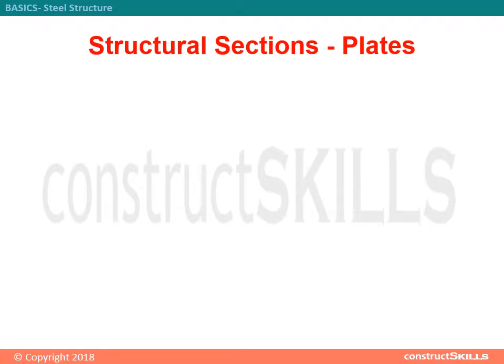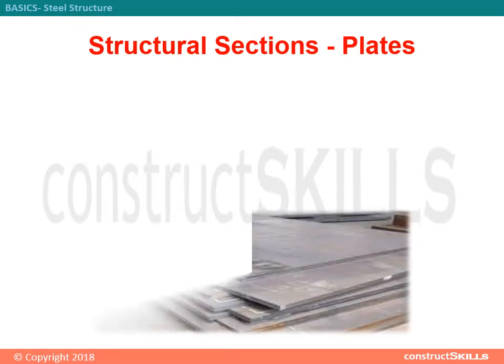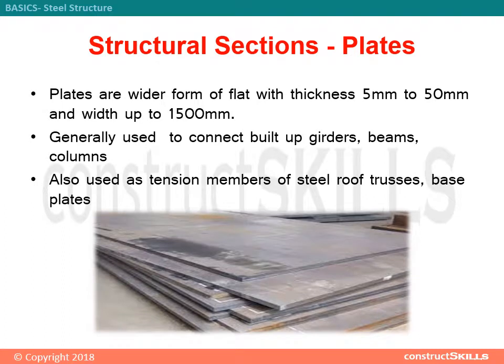Structural sections, plates. Plates are a wider form of flat with thickness 5 to 50 mm and width up to 1500 mm. They are generally used to connect built-up girders, beams and columns. They are also used as tension members of steel roof trusses and base plates.